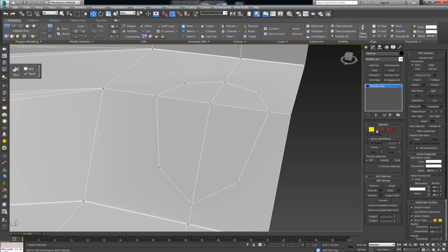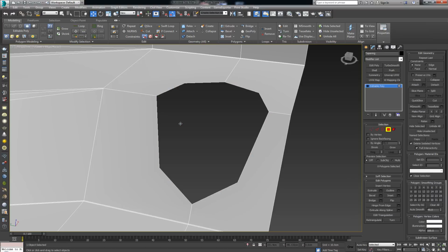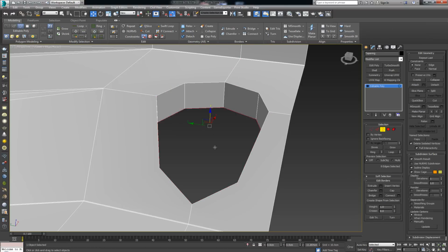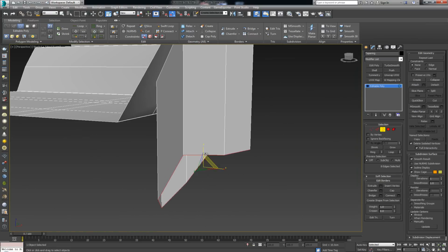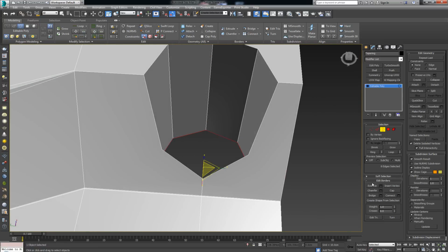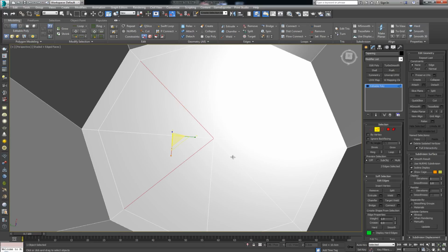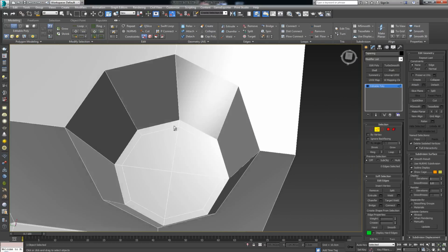All right, let's select all of these guys, delete, hold down shift, pull it downwards, again scale it upwards so it gets flat, where I can just make planar, but still this works just fine. Again, I'm going to hold down shift and scale it in once and twice and collapse. That's going to leave me with this form. I'm going to again select all of these guys, Control Backspace, and there we have quads at the bottom.